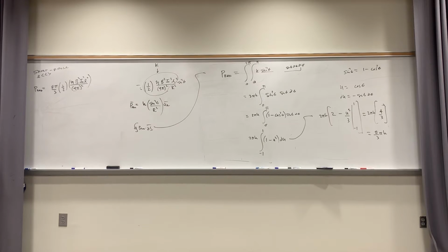Got it, everyone? Now, that's the total power, and I told you before, you don't get something for nothing. The electrical current that is causing the acceleration of charge is creating and launching photons of energy. The only way that can happen is if the wire has some resistance, because remember, this is real power being lost, right? This resistance is called a radiation resistance.